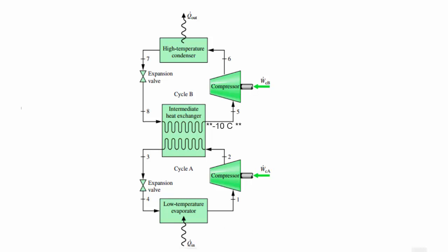And then in the heat exchanger, when it releases the energy, which is Q out, it could be, you can say, 15 Celsius, and that 15 Celsius will be the evaporative heat energy for the second refrigerant cycle, which is above the heat exchanger, and it could be with the refrigerant R134a, and this refrigerant might boil at 15 Celsius, and then the same principle goes on, and these two cycles work for two different environments.